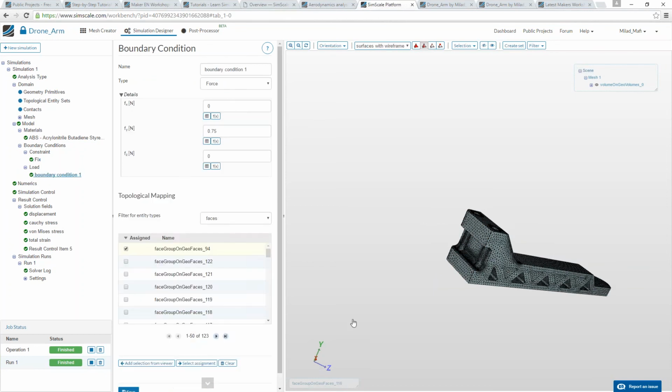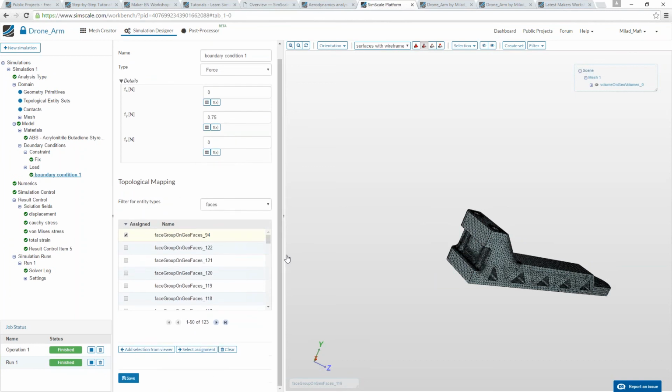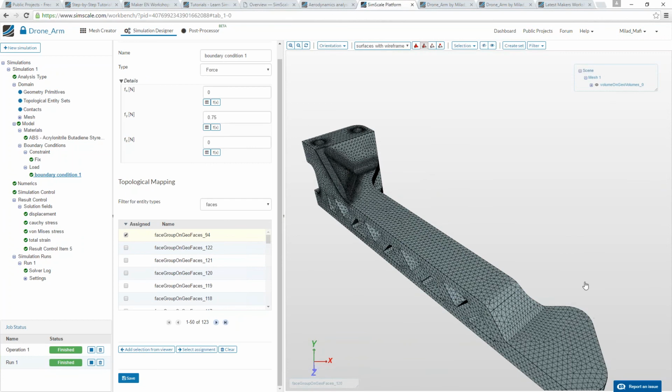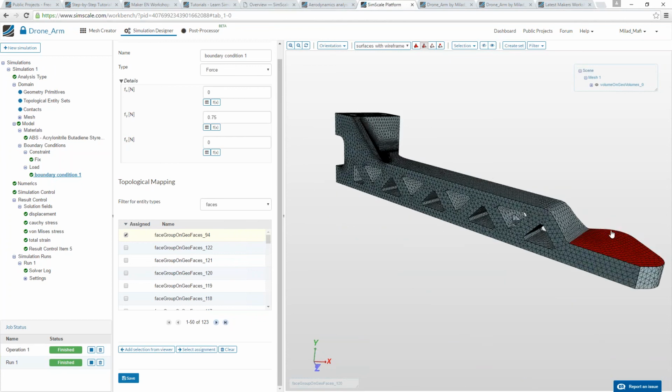And for the load, as I mentioned, I just simulated the load generated by the propeller on this drone for the whole drone, divided it by 4, and added it on this face because it must be normal to this face. Great, Alex. I hope this answered your questions. You will learn also next week how to develop your own boundary conditions.